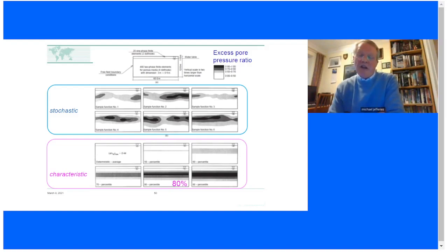What we're going to do then is run an earthquake past those finite elements, and we're going to use one of these constitutive models that computes pore pressure, and it's sensitive to void ratio. So we can look at the effect of void ratio on the excess pore pressure. And you can see the scale for excess pore pressure on top right. In essence, dark black is full liquefaction. Pale gray is an RU of 0.6 to 0.7.